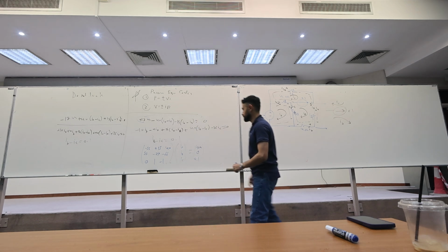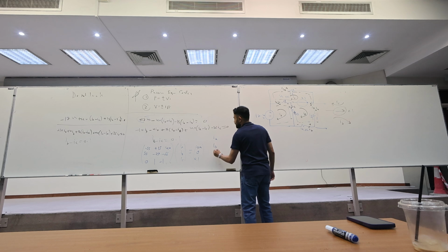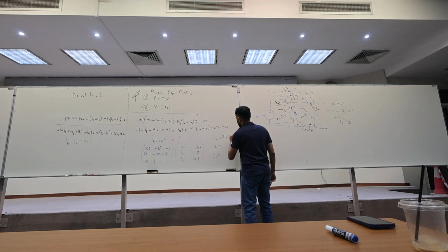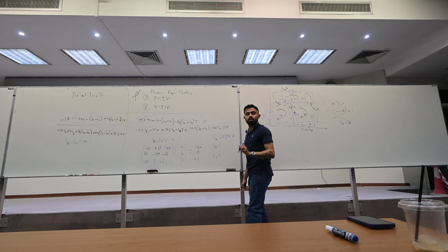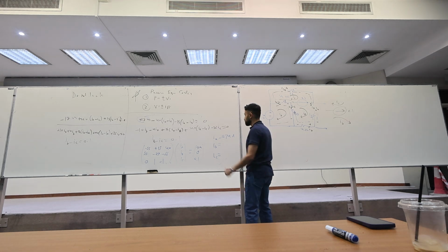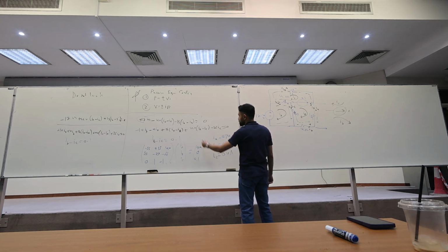System solver. What is IA? What is IB? What is IC? IA equals 0.74 amps. Don't forget the units. Even in the test, don't forget the units. Take it as a good habit. What is IB? 0.5. And IC? 0.4. Check: 0.5 minus 0.4 is 0.1.